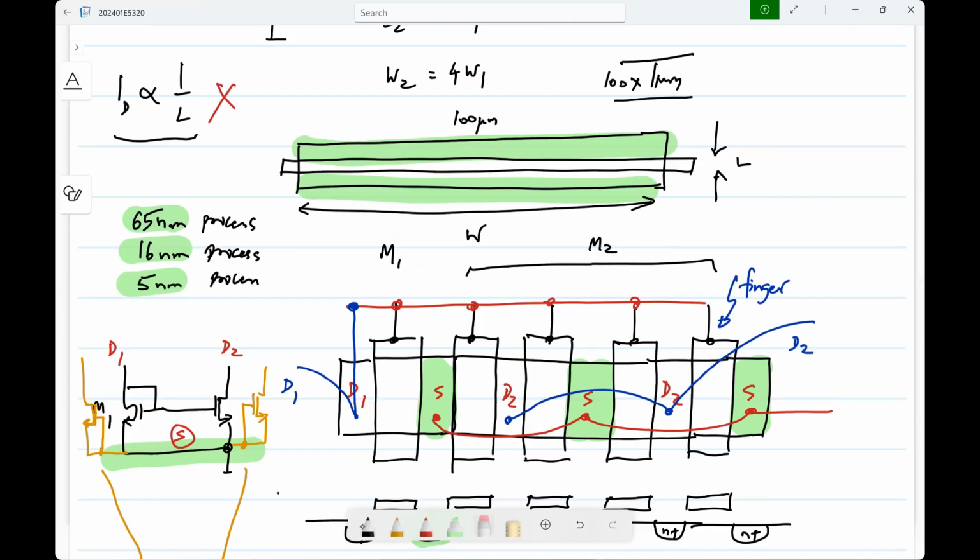Any questions? Systematic mismatch is there because the properties of the component depend on the physical environment and so on. And also you have simple formulas for some parameters like the resistance, etc., which do not actually hold. There will be other extra terms. So to combat that, basically you have to use identical components, right? Unit element based design. This is something that you will need to know, and those of you who will go on to do IC design will be practicing this.